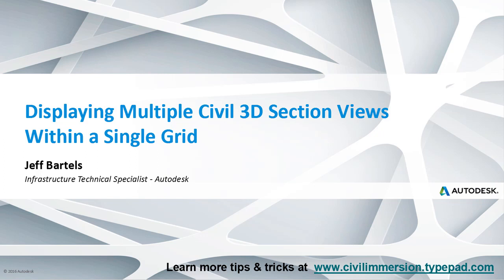Many times when creating Civil 3D section views, each view will have its own grid. In this session, we'll learn how to display a single grid that multiple section views can share.